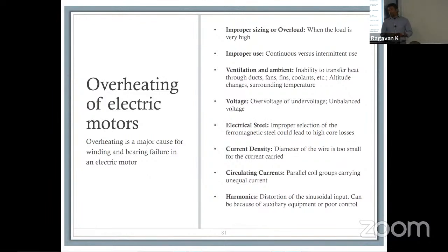What you never want to do is put your wrist or hand on the shaft or the coupling, because those motors, if they're rated for, let's say, 2 to 3 kilowatts at 100 RPM, will take your wrist right with it. While it sees the extra load, it starts to crank up the current. As it increases the current, it will snap your wrist very easily. The point I'm trying to make is that improper use is something people often ignore or overlook. It's not always the case, but it's definitely something you have to take into account as a manufacturer.